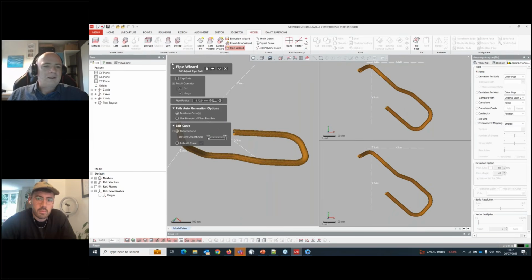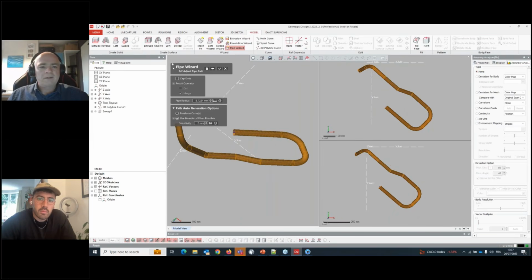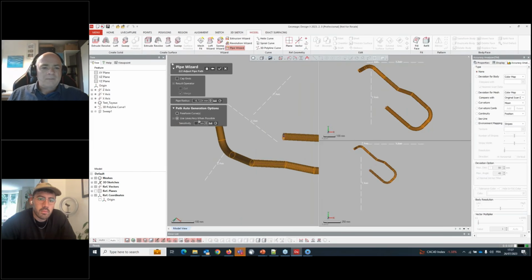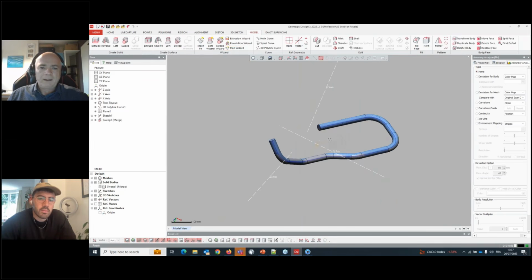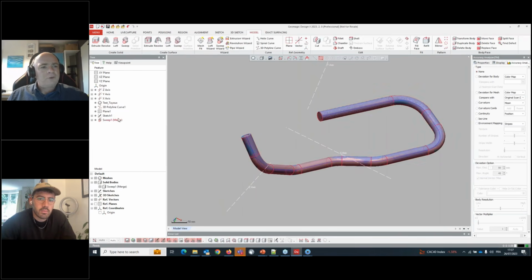The only difference here now is you can ask for lines and arcs, and now it creates a nice pipe definition with a value you write in the pipe. And here you have all the lines and curves each time. You can ask two cap ends to make a solid body. And when you press OK, you have the new feature, which is here, the 3D polyline curve.